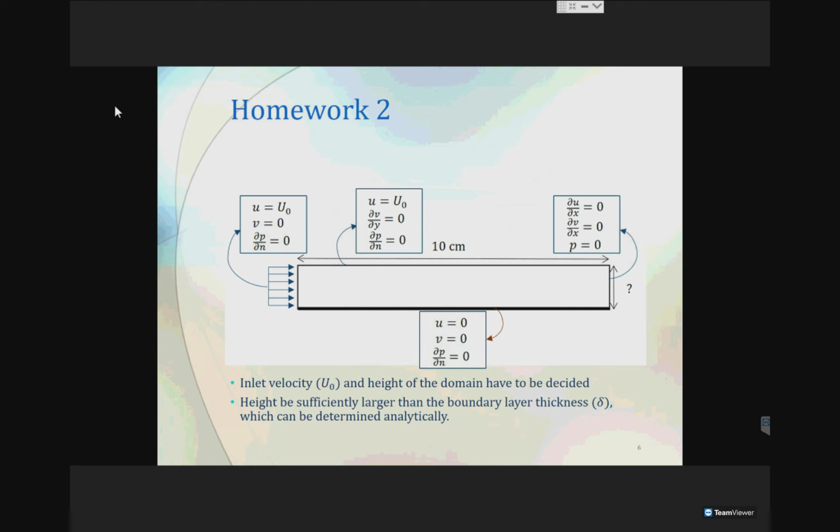So you will notice that over here, when we are fixing u and v, we are leaving the pressure as having a 0 gradient. On the other hand, on this boundary, we are having both velocities as 0 gradients. So now we can fix the pressure at this point.